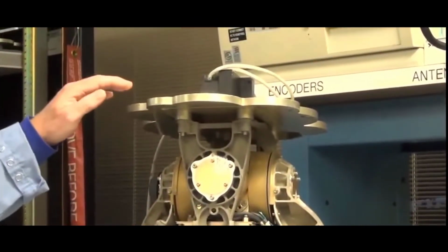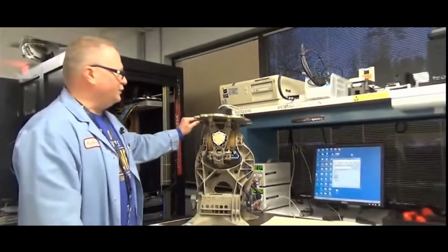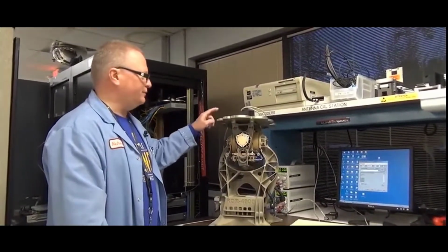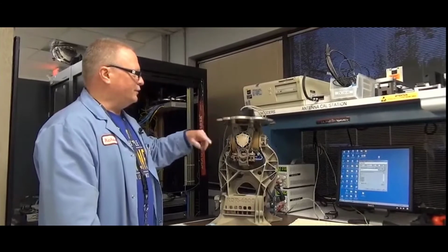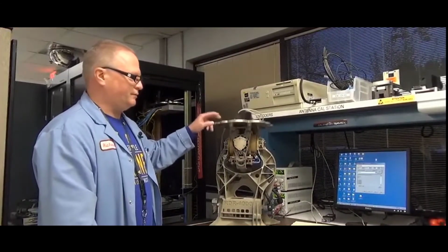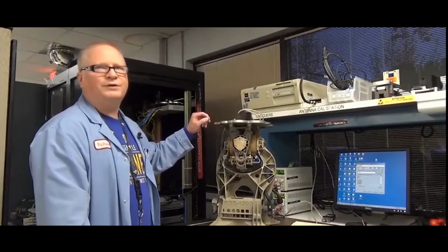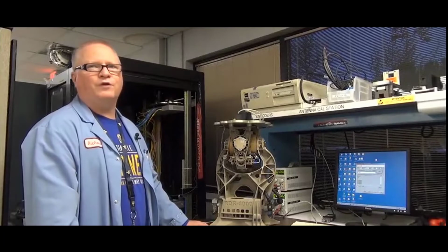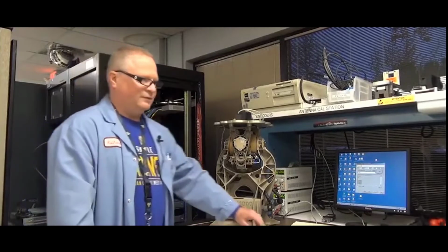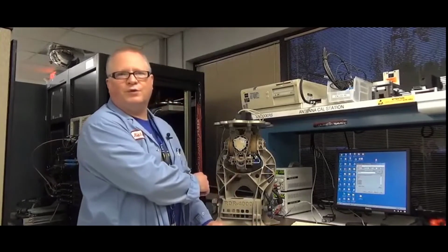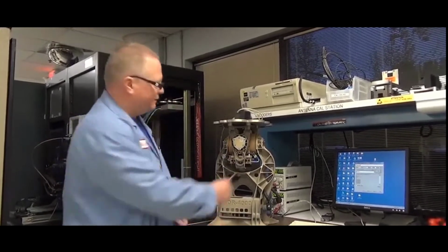When it's at the 0 position, you should feel resistance when pushing against the energized motors. On this one, you can see that there's very little resistance in your azimuth, and this is also an indication that you have a problem with resolver feedback. To verify this, we're going to want to get a close-up on this point right here.